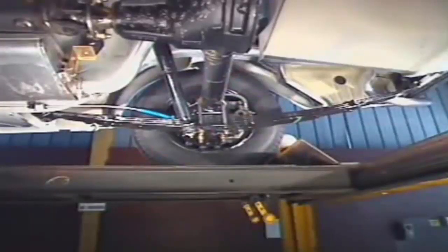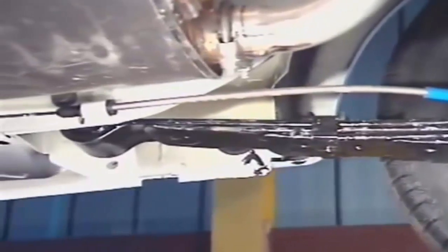It is usually controlled by mounting the axle housing closer to the fixed shackle point, so that the spring's front section is shorter than the rear section. The short, stiff front section resists twisting, and a bump stop above the final drive housing can also be used to restrict upward motion during acceleration.